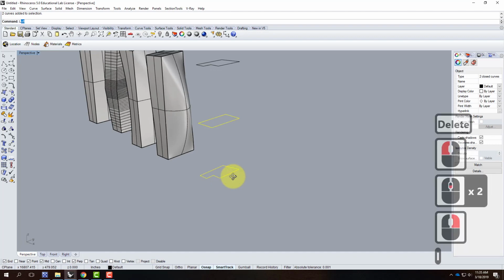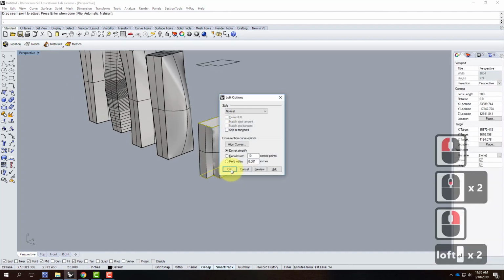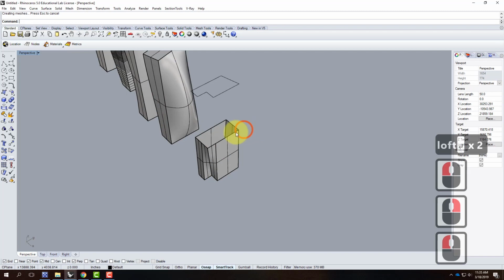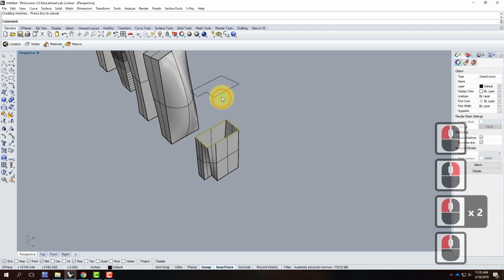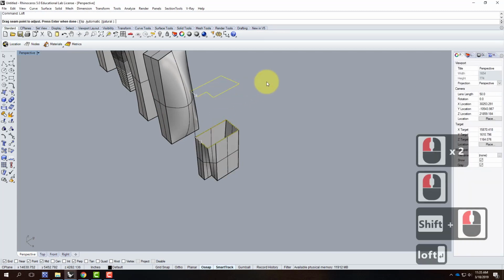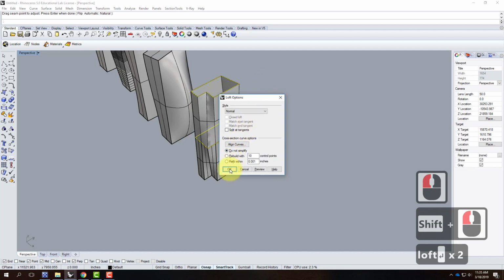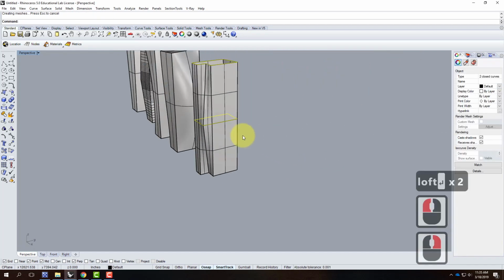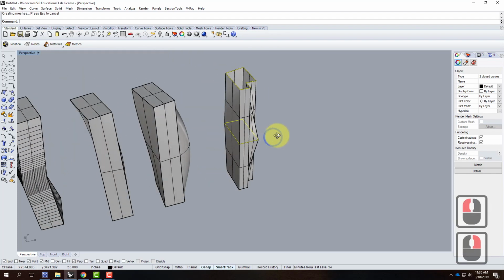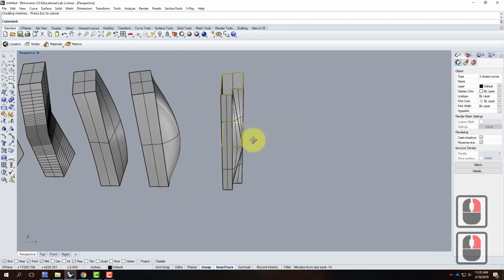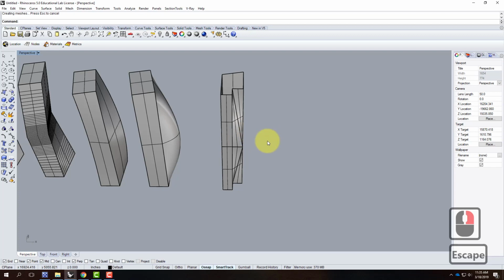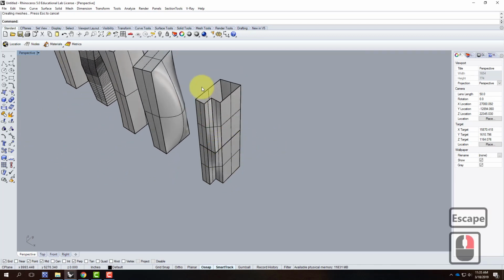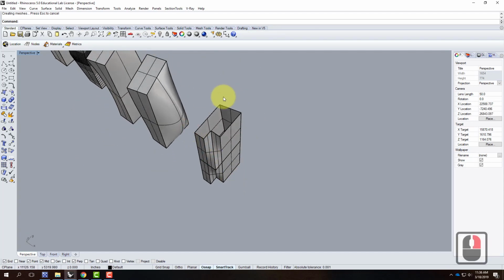We'll loft those together like that. Then I'll take these upper two from here to there, and I'll loft those two together. I'll say OK. And so that gives me this little kink that comes out. And that may or may not be attractive. So we'll take that. Then I can perform a cage edit of this whole thing. Though the truth is, it would be better if I had a top on my shape here. So I could go ahead and create a top first.